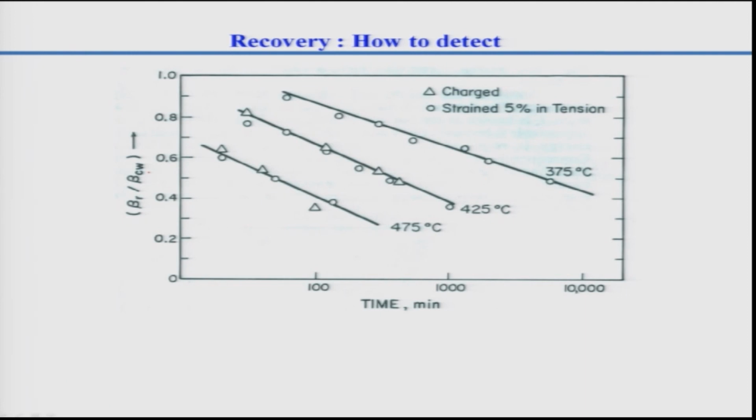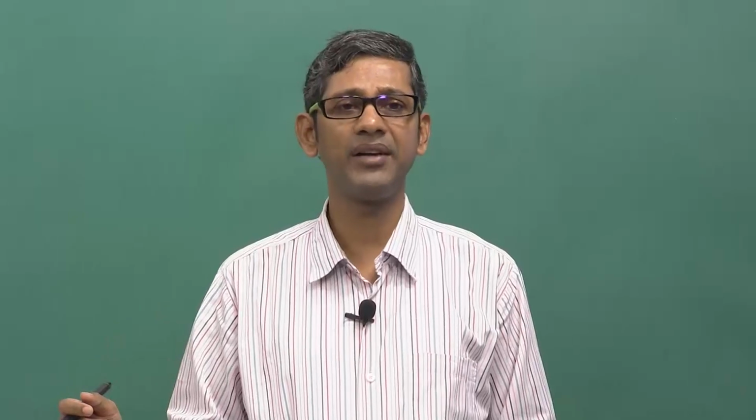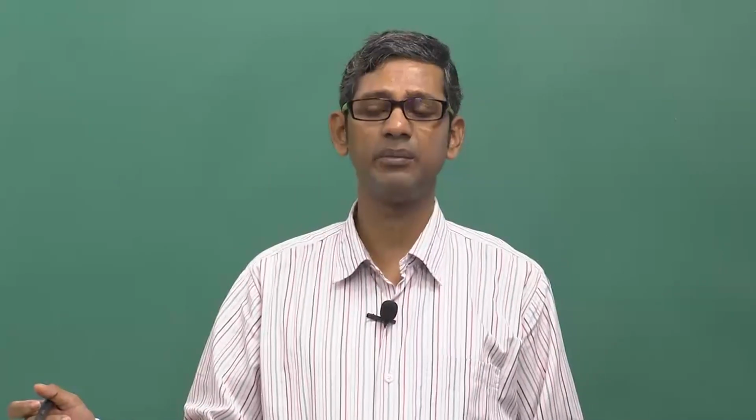As you see, the ratio is slowly decreasing as you go along the time scale. That means the strain inside the material is slowly decreasing, because the full width half maxima of the peak in X-ray diffraction, when the grain size is not changing much, tells you the strain induced in the material. So this is the way one can calculate the reduction of strain in the material.